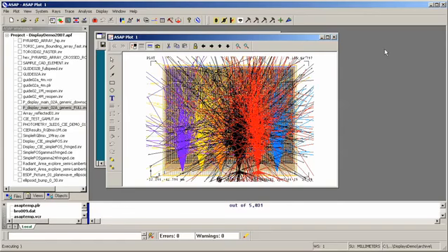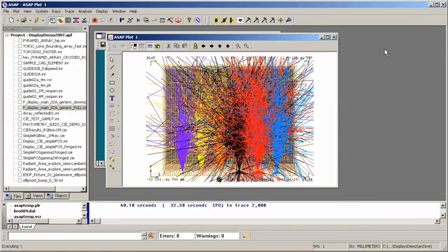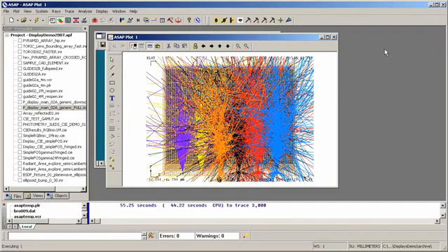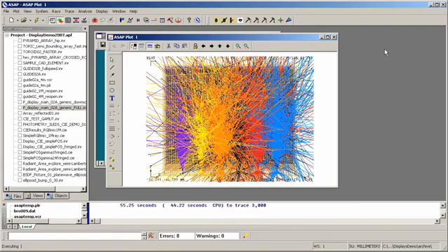And the first rays we see are rays that are simply totally internally reflected, but we also have a scattering process on the foil sheet on the bottom. It's a reflector, but it's not a perfect reflector. It's a scattering reflector. So now we're seeing scattering results off the bottom surface, which further causes the rays to be propagated across the light guide, and it also causes some of the rays to be directed back towards the origin, which further helps to fill in the gaps between the LEDs near the launch point.